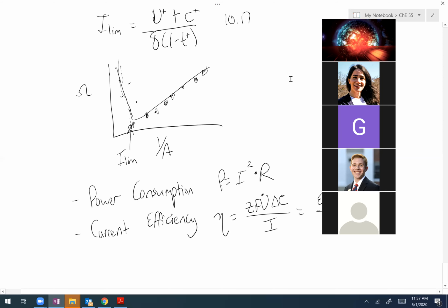The only cases where it doesn't is when we look at other processes like electrodeionization, because we're kind of cheating Ohm's law a little bit to our benefit. With a bipolar membrane, it's going to follow it a little bit, but you're going to see an increase in those power requirements, primarily because you want water splitting in that situation to get the acid and base formation. Awesome. Thank you. Of course.